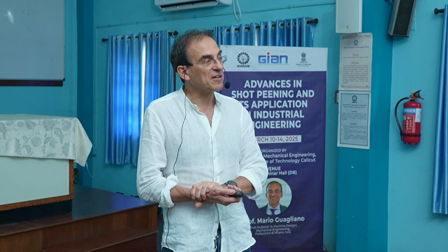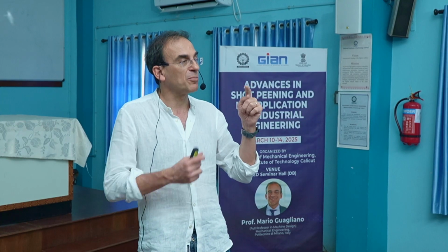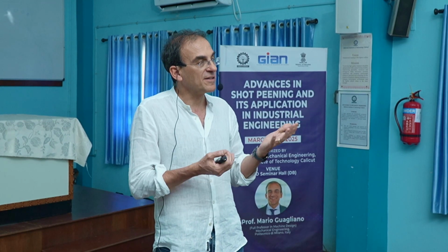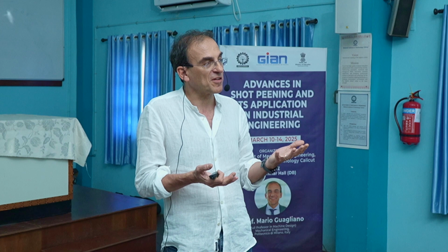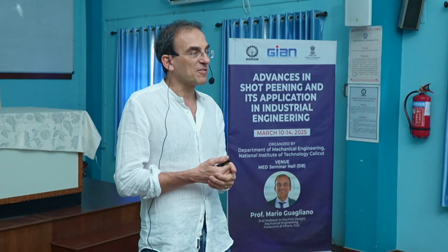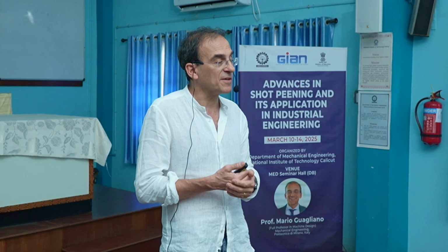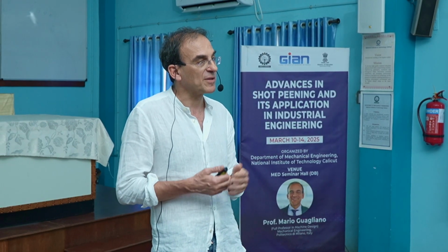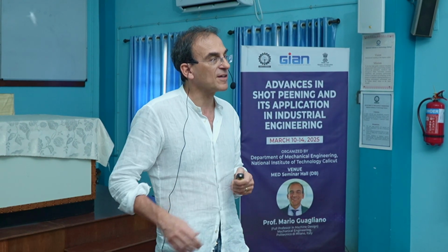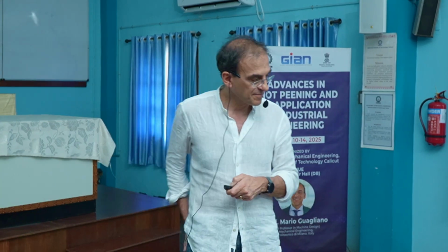Today there are more modern detectors, position sensitive detectors, and they permit to measure the intensity of the X-rays not in one single point, but in a finite area. And it's quite useful also for residual stress, because in this case we don't need to move the detector to have a 3D or 2D view of the intensity of the X-rays, but just one exposure is enough, because we have a two-dimensional window that is recording the signal.